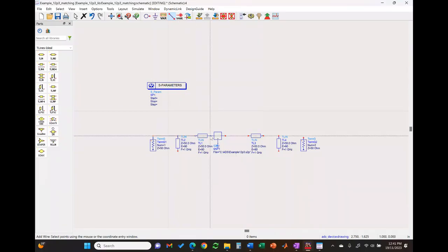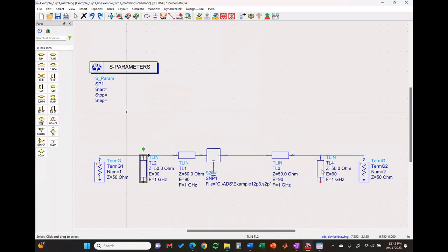Again, I'm just creating so much spacing so you can see all the text. Then I just connect everything using transmission lines. So this will be the input side. This will be the output side. Now you can see that these 2 elements have one port that is not connected, this one and this one over here. When they are not connected like this, this means they are open circuit, so you just keep them as they are. I'm just going to center everything in the middle so you can see how the problem looks.